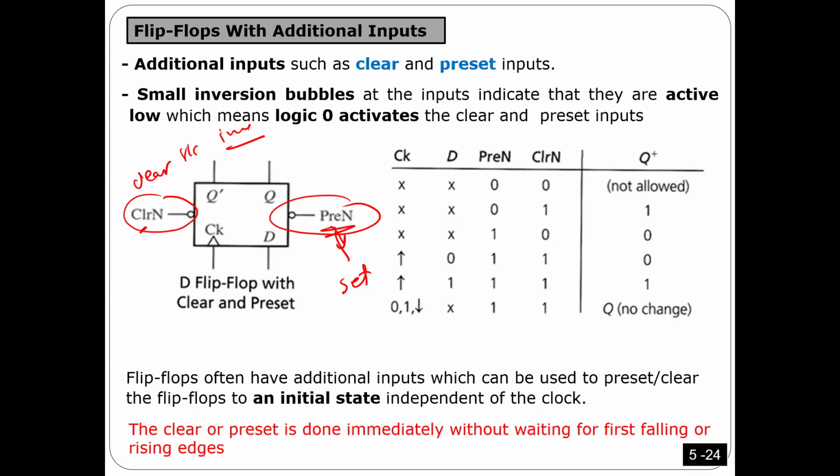Okay, guys? So again, let me say it again. We can add 2 more inputs. These inputs are going to set or clear immediately, not waiting for the clock. And this is not the normal operation. We use it just in specific cases, like for example, just initialization. Okay, I don't want to wait for the clock. I want the action to be taken now, not wait for the clock. Like initially, it's not the normal. Okay, so that is why we can add 2 inputs this way.